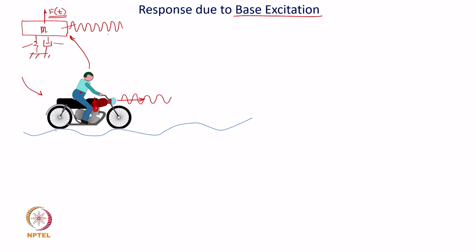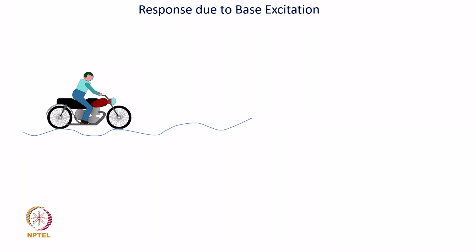For a compressor or a huge air conditioning unit, the excitation can come from the ground and it will excite that whole system. If you have a heavy forging hammer nearby, that forging hammer is going to generate excitation coming from the ground, and your other sensitive equipment or machinery can get excitation from the ground. That force somehow gets transformed into the motion of the base. Excitation due to earthquake is nothing but a base excitation to the building structure. So, what is the way we should model this system for such kind of excitation coming from the base? That is the job.